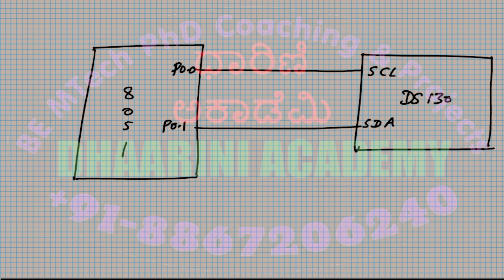You can see that there will be a crystal connected to X1, X2, ground. The VBAT is the battery, where you connect a 3 volts battery. So it has nothing to do with the programming, so you don't have to worry about that. All other parts are already right. You have to make a proper circuit. Yes, so everything else is done.